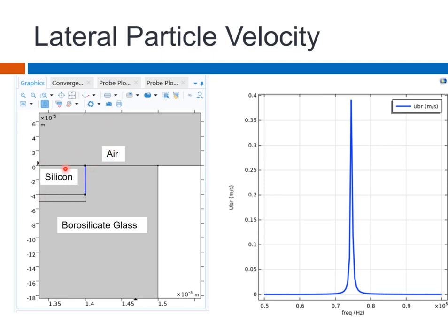And then you have air loading on the front of silicon. So that air loading is going to depress the silicon for the static analysis, but the silicon is held fixed at the rim, okay, where it is bonded. So just to check, when you apply the electrical signal between these two plates, the AC particle velocity, you can see if you calculate the average velocity over here, then it's not zero. The AC particle velocity is not zero. So that is finite, and it's a very high Q peak, which shows there's not much, I don't know, loss.